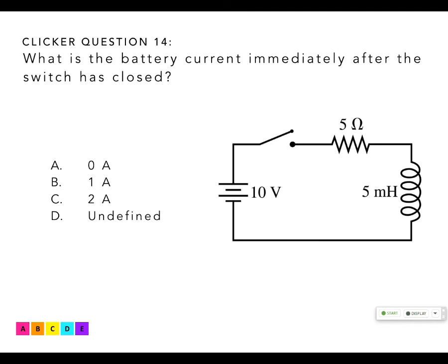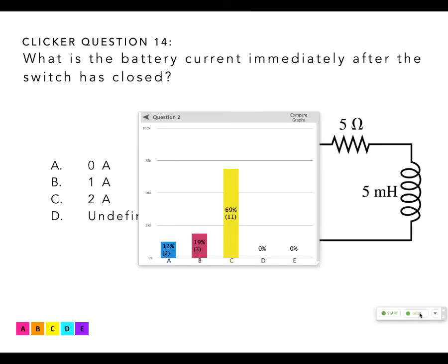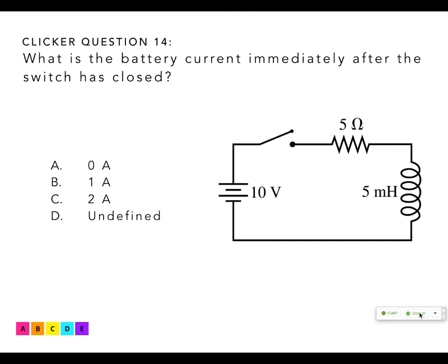So we'll discuss a little bit again. Okay. All right. So, how does an inductor work? When you flip this switch closed, what's happening to the current? It should be increasing, right? So what does this do? Resist. Is it a big increase? Yeah, you're going from 0 volts to 10 volts. So you have a large jump in what it's trying to do. This thing should put up a big resistance because it's a fast change.